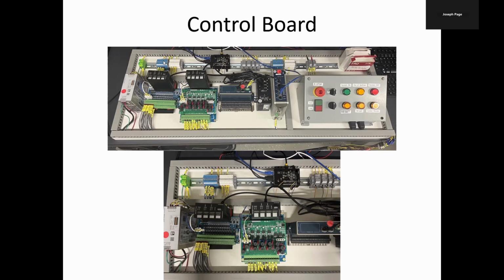We have blue terminal blocks for 24 volt positive, white terminal blocks for 24 volt 0 volt, and gray for signal. These gray terminal blocks are for the sensors in the chamber. These gray terminal blocks are for the power for the solenoids, which go to the discrete out board and are controlled by the Mark 6E controller in the HMI. Everything is run through these cable trays. Power comes in on the left, and the wire harness comes out on the right.